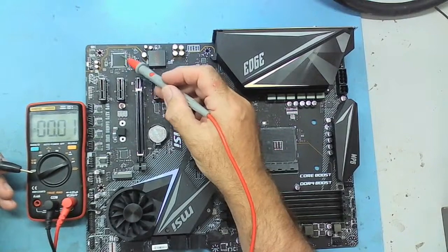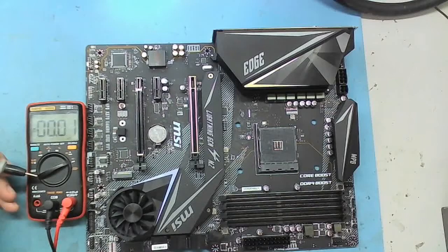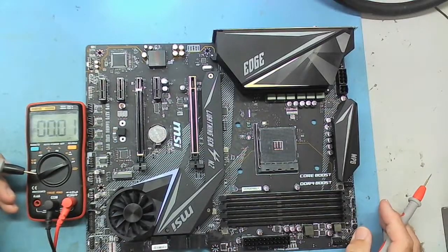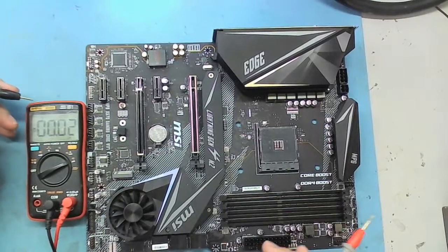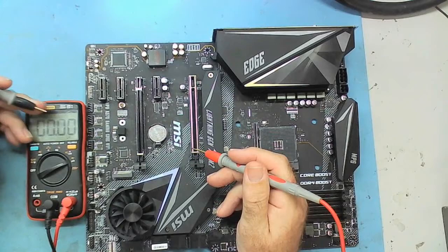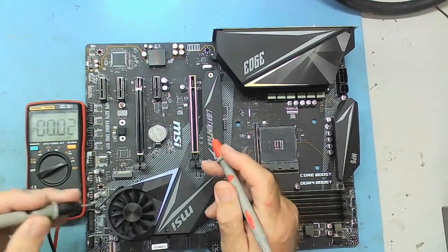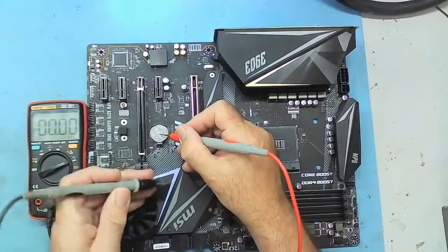That's an SIO. That could be the real-time clock. North bridge under here, it could be here. Is there a south bridge on this? I'm not very familiar with AMD architecture. In fact, I haven't really looked at them. This is the first for me. I've done quite a lot of Intel boards, but I haven't really done any of these. So, normally speaking, I'd expect to find about 10 microamps on a good board.